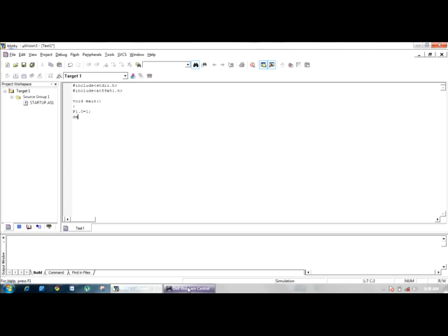So I am going to give delay, which is an additional function that is to be written, and let us write it at the end of the program. Now followed by port 1.0 equal to 0. Now I am giving logic 0 so that the LED is off. Again I am going to give a delay which will tell the controller for what duration the LED should be off, and close braces.